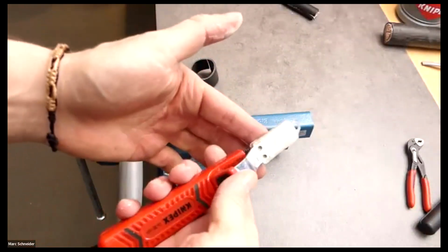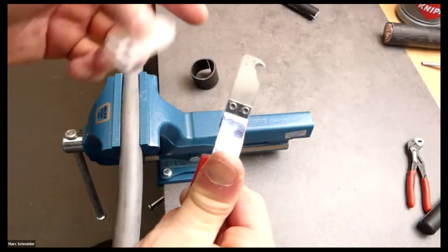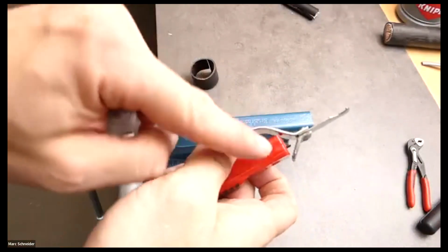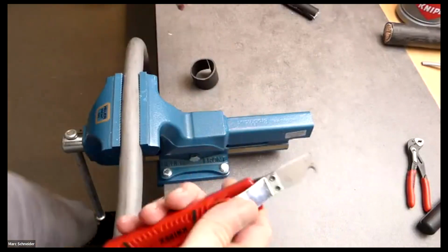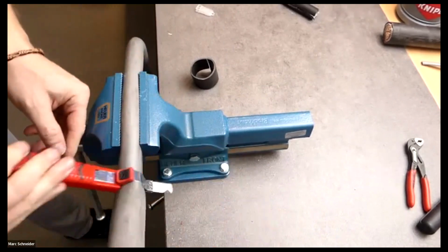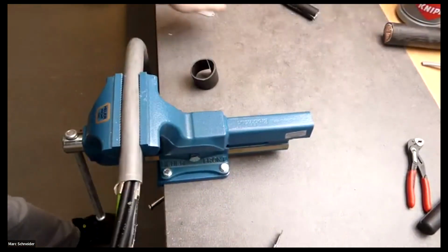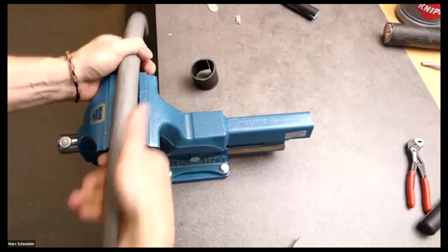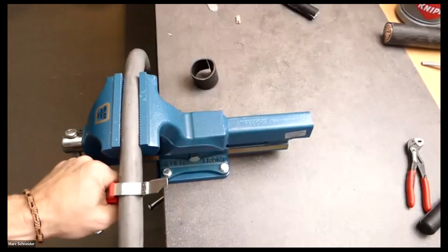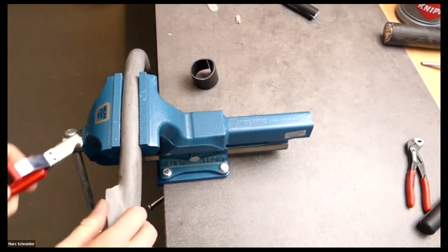So this here is the other cable knife. Here we have the protection cap for the universal blade. Here is the reel to adjust the size, the depth of the blade. So now, again, I turn it, and you see, oops, length cut. Again, I put it here, and now I turn it, careful with the knife, and you see here, you can do the length cut with the blade.